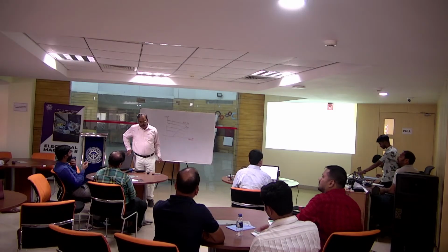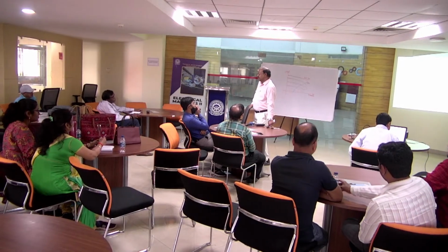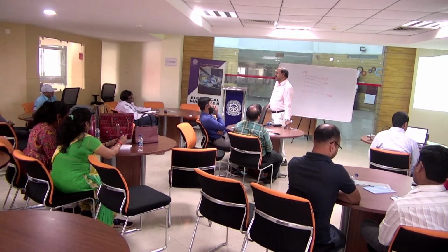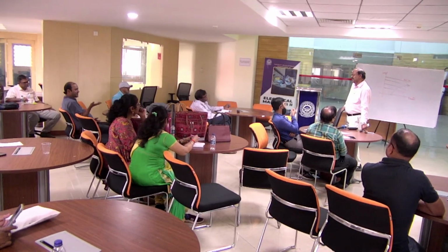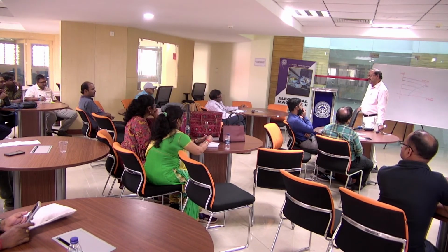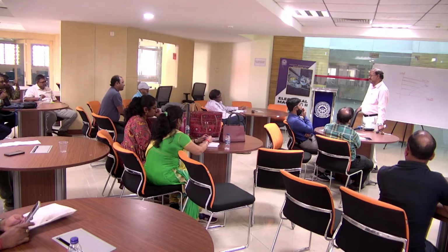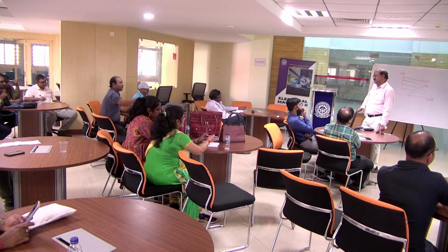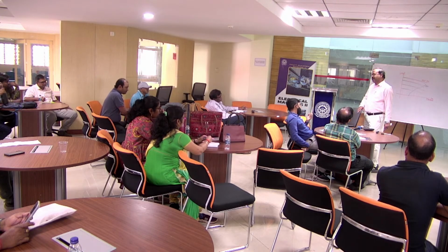First of all, in a transformer and an induction motor, whose power factor is better? Why? In a transformer, it is static, so losses are very negligible. Here, the air gap is more, and that is why the yoke loss is also there. Many losses come into the picture. That is fine, good answer. So that is the point.